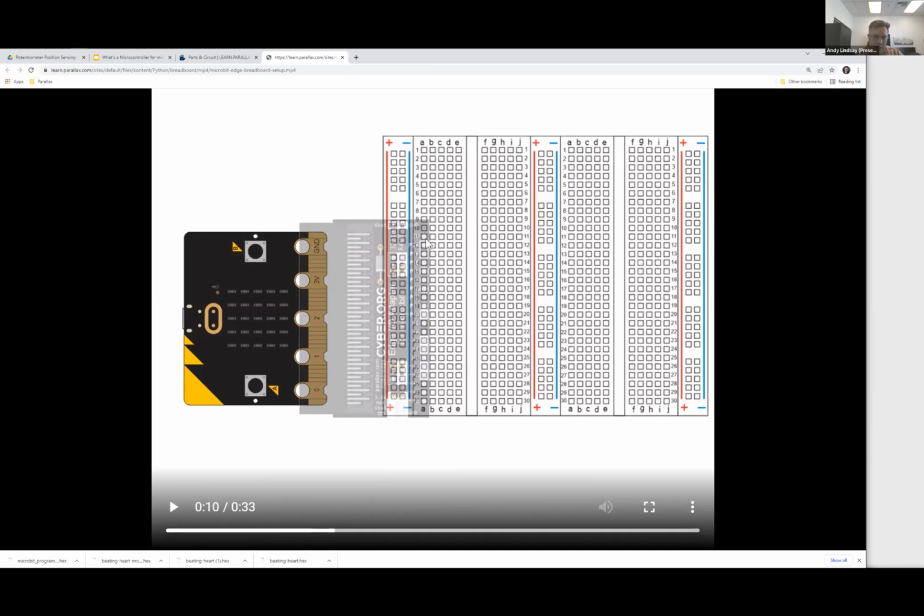So anyway, that row of pins needs to be started in those column A sockets, with the P0 labeled pin on the adapter going into the A30 socket on the breadboard.